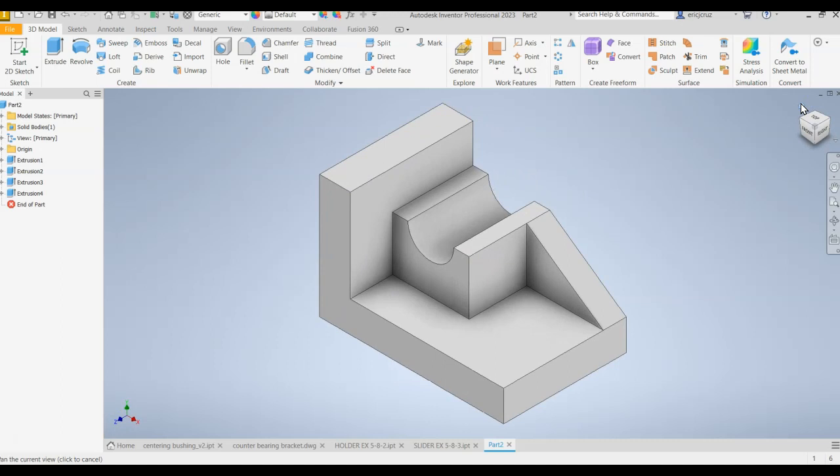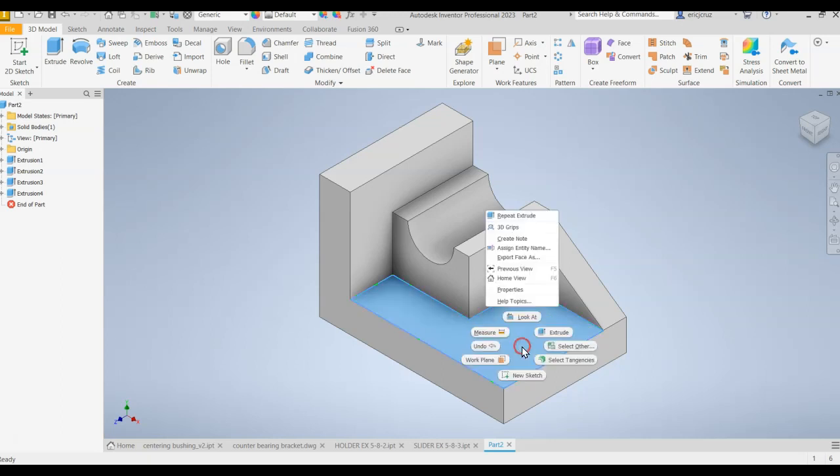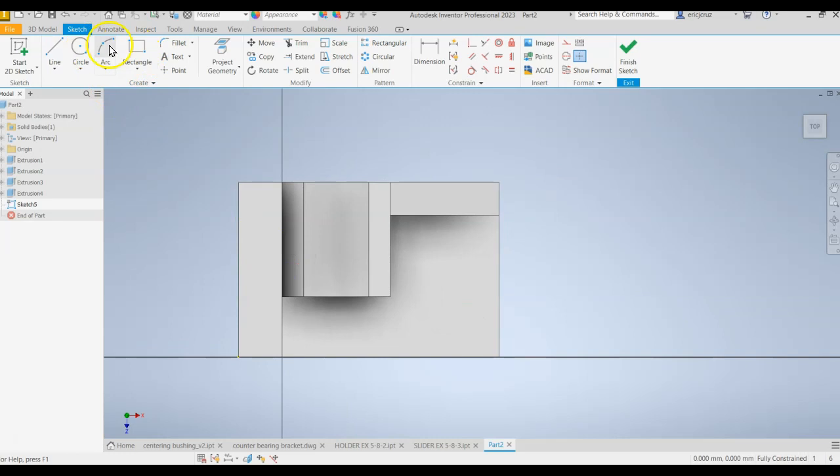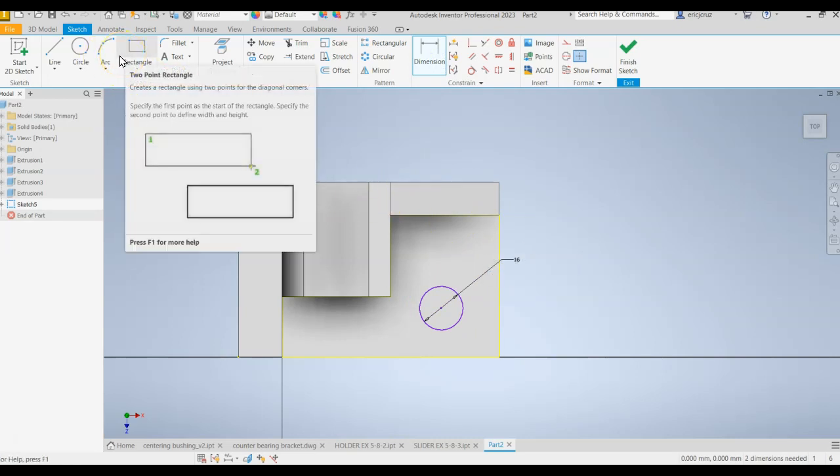Now we can make the hole here. So go ahead and click on that surface, right click New Sketch. Project the geometry again. And this time we're going to draw a circle with a diameter of 16. Oops, I accidentally clicked. Let me click Dimension. That should be 16. And it should be, let's see, where is it placed?